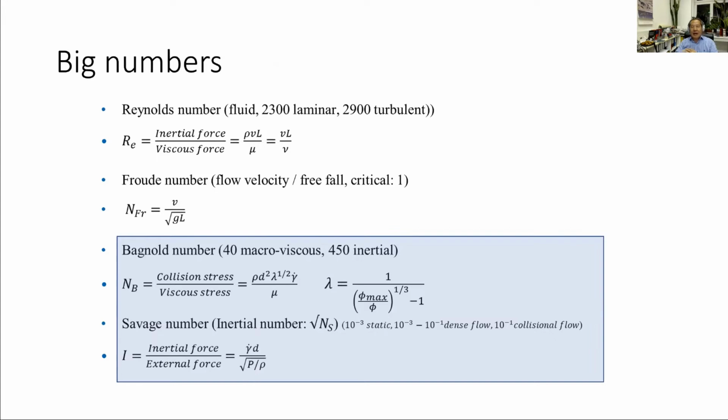And then if you have a look at these results, the strain rate covers a large spectrum, several orders of magnitude. And you also see the solid fractions in a very large range, from very dilute flow to dense flow. I must say the dense flow is more relevant for granular materials.